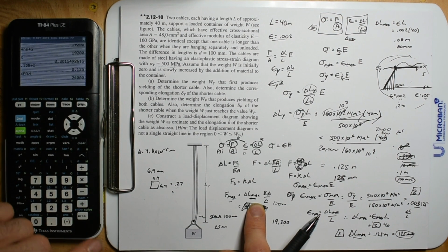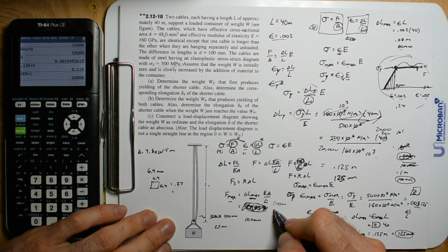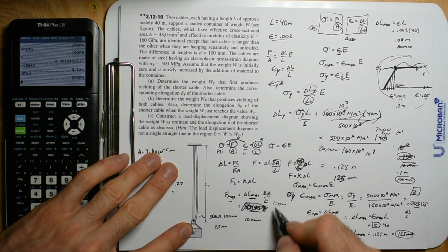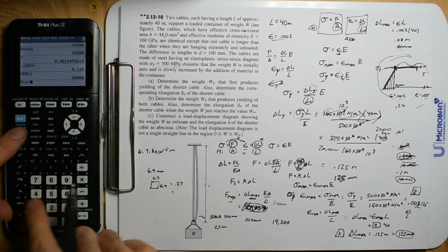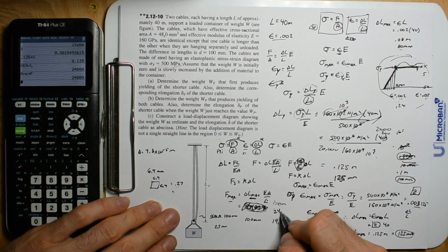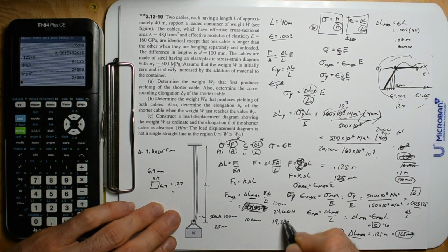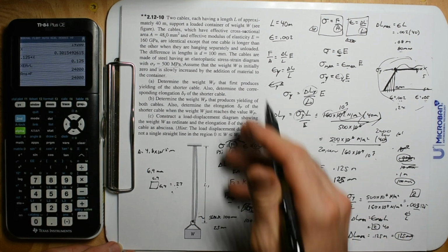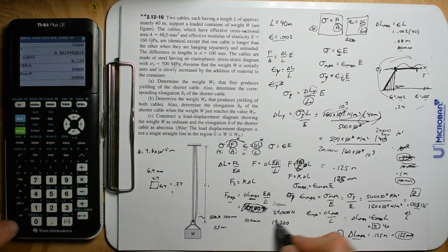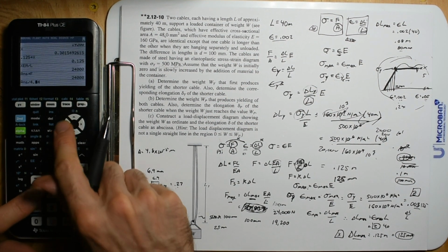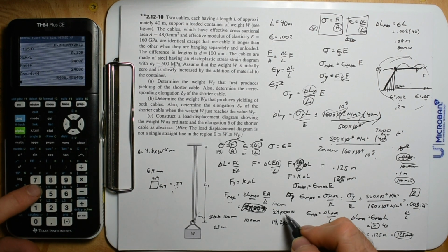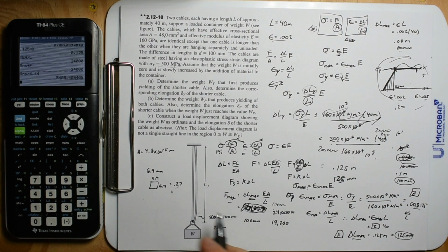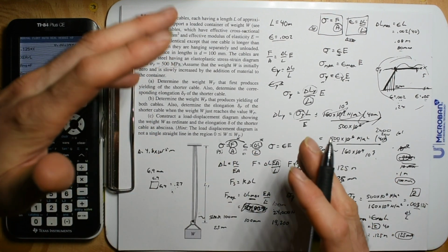So this will give us the right answer. If we stretched one cable 125 millimeters, we would get a force stored as F of 24,000 newtons. It's not even pounds, and I don't even know why I thought that was pounds. We're all in metric. This is 24,000 newtons divided by 4.44, which is 5,500 pounds. Cool. So we got a quarter-inch cable, basically. Two quarter-inch cables that are pretty damn strong.